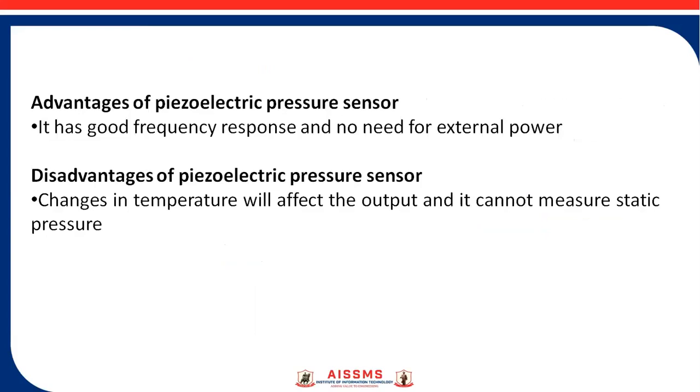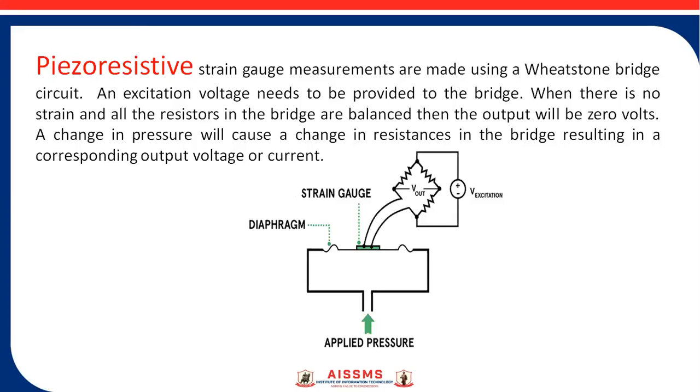Advantage of piezoelectric pressure sensor, it has good frequency response and no need of external power. And disadvantage of the sensor is change in temperature will affect the output and it cannot measure static pressure.